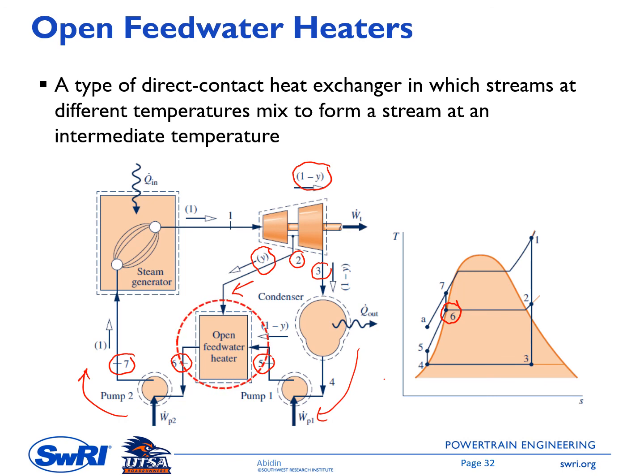Okay, so why do I say reduced fuel energy? Because when the steam enters the steam generator, the state is not at 4 anymore, but it is at 7. So it is at higher initial energy, so there will be a reduction of the fuel energy to heat up this water to produce the steam or the superheated vapor. Once again, to make sure that the system efficiency increases, the operating condition is in such a way that the reduced fuel energy more than offsets the reduction of the turbine power.